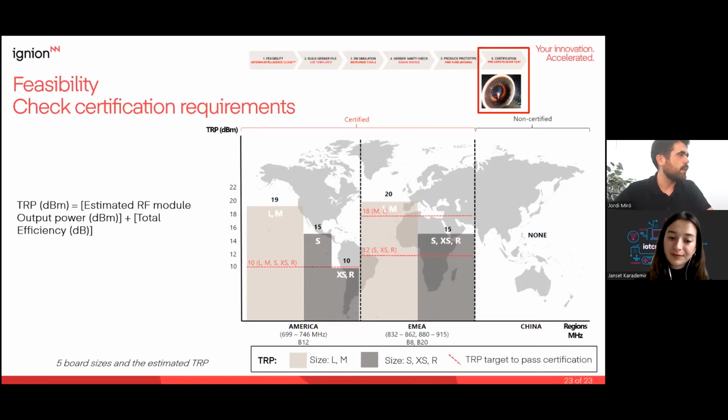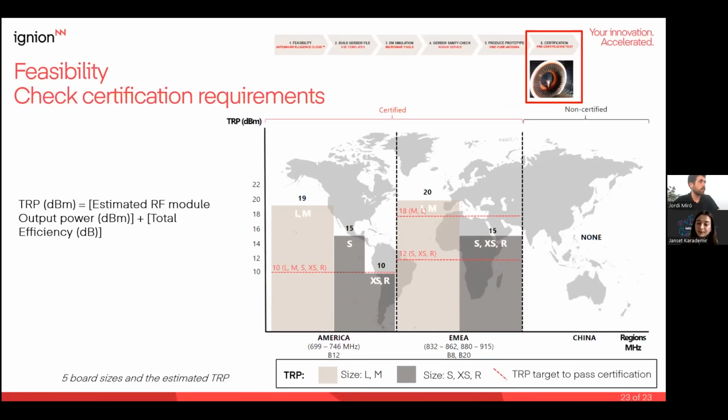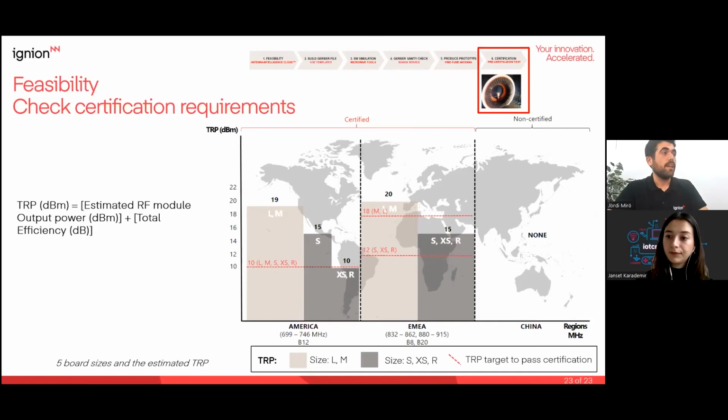If not, Madhu, send me an email and I can explain a bit further. You can evaluate, for example, the Trio mXTEND in a multi-port configuration, but then you need a matching network for cellular and another for GNSS. An alternative would be an active matching network with a single port, covering cellular and GNSS, but that is another story. It is mentioned in the Thingy:91 application note.